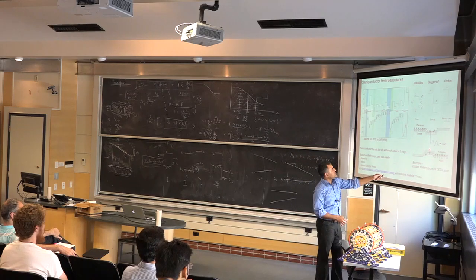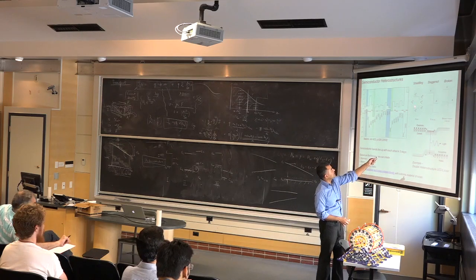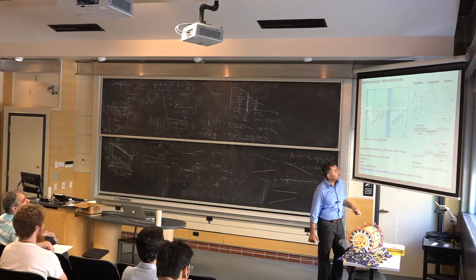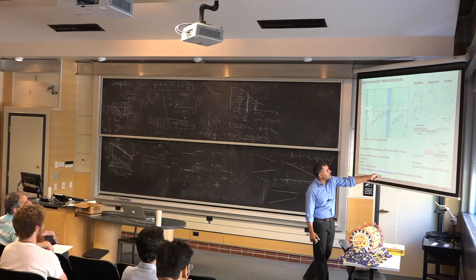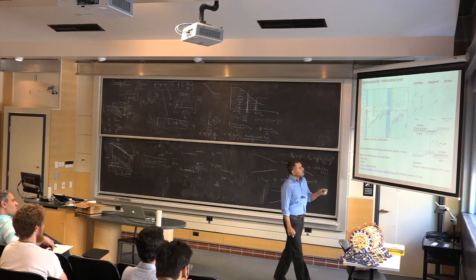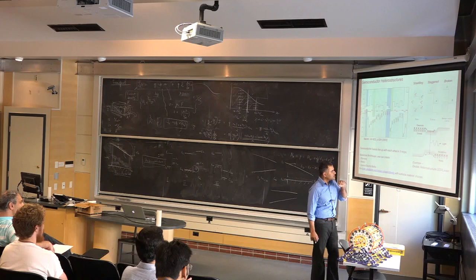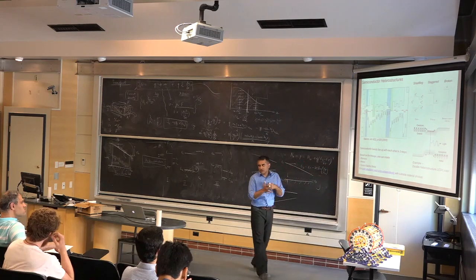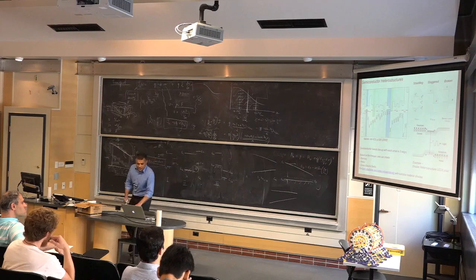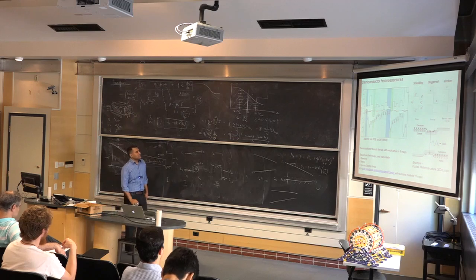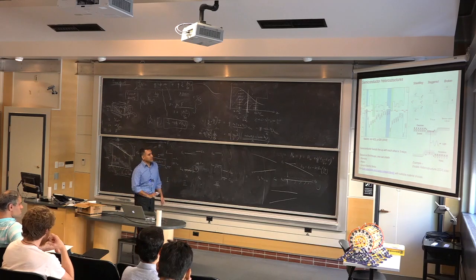You can take a narrow gap material and put two wide gap materials of type 1 next to each other, and this is a quantum well now. You can thin it down very small, and you inject electrons and holes, and generally this is the heart of lasers and LEDs and that sort of thing. Quantum well design, and in fact, a lot of transistors today also use this. Electrons get trapped, holes get trapped because there are barriers on both sides, so you have a lot of room to play with these structures. Okay, good. And we will look at them in reasonable detail when the time comes for those particular devices.